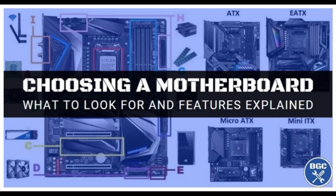The primary drawback of this board is that it does not have any accelerated graphic port, AGP, ports, resulting in a connection to PCI that is made directly. The new low-profile extended, NLX, boards are where issues present in these motherboards have been addressed.